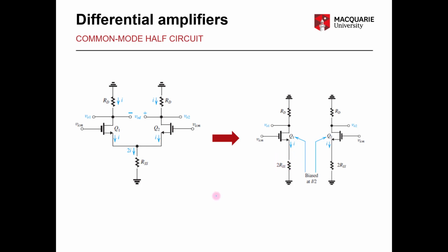So this is due to the fact that in our original circuit we have a current source I, which was shown to have the resistor RSS in parallel. Now, as our line of symmetry intersects our current source I, this resistor in its current configuration would break the symmetry between our two half circuits.